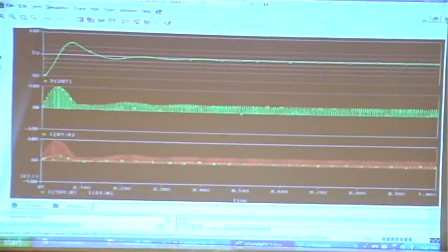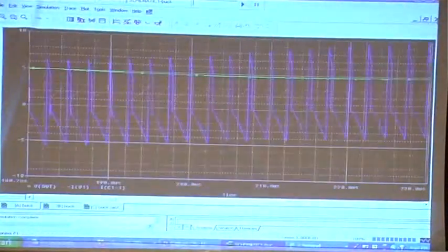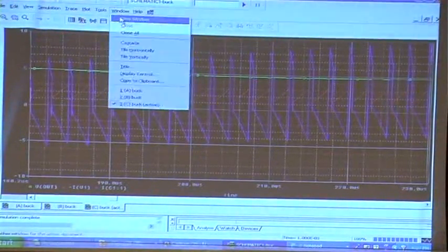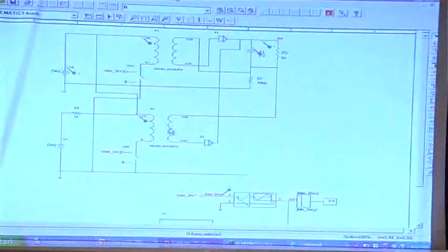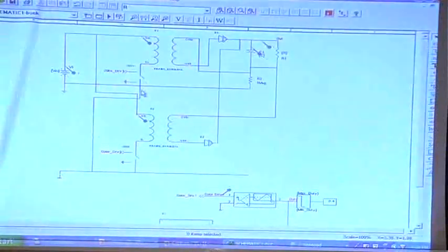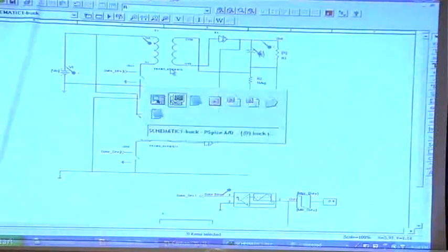In practice, for the DC source, are there two sources or just one source? One source. So let's see if we can go ahead and plot. Oh, I see what it is. You have made two sources, but in practice it was just one. Yeah, it is one. We have a 1K resistor here. Actually, you can take this out because this is connected here. Yeah, this is connected now. So we can actually go ahead and rerun this.